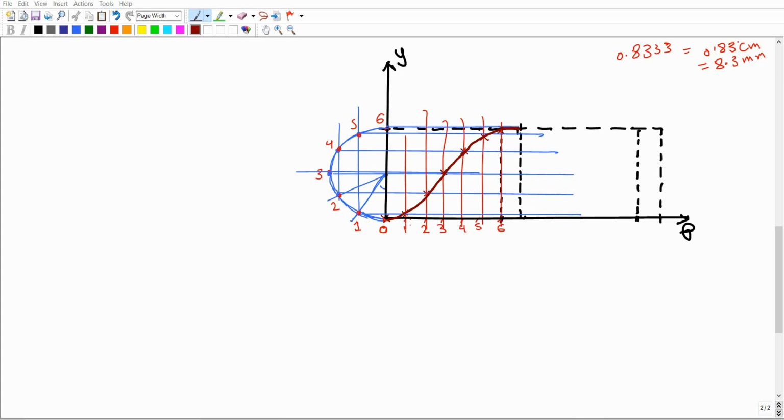Since we have the simple harmonic motion, here it is already distributed over 50 millimeter lift and 150 degrees over the cam rotation, and we have the same type of motion over the same periods. We have the same 150 degrees of the cam, and the 50 millimeter of lift. It means that we can make use of this circle to generate, and we can use the same circle for generating the simple harmonic motion for the second return period.